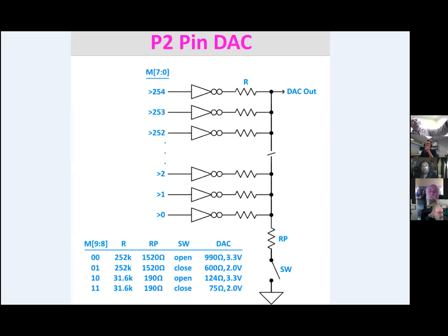Well, you see the point of this topology, it's very simple, so it's very fast. It settles in like a couple of nanoseconds. Fantastic. And how accurate is the 8-bit DAC? It has an inherent linearity of about 10.5 bits. I see. Okay, but it's an 8-bit DAC. It's just an 8-bit DAC. Is it monotonic? Yes, absolutely. 10 bits, yeah.